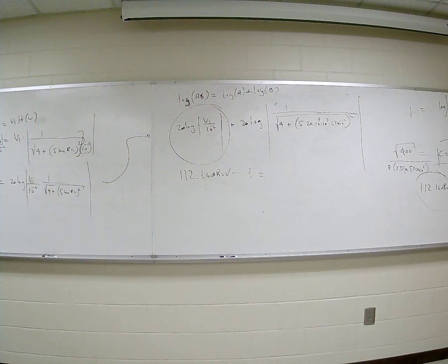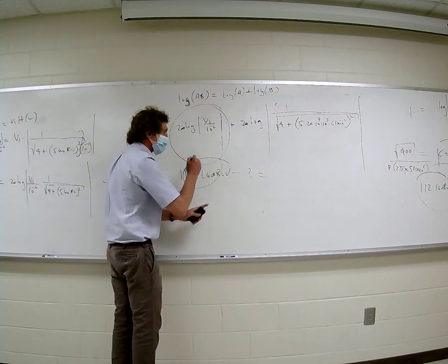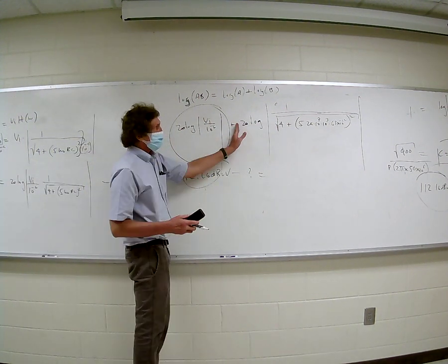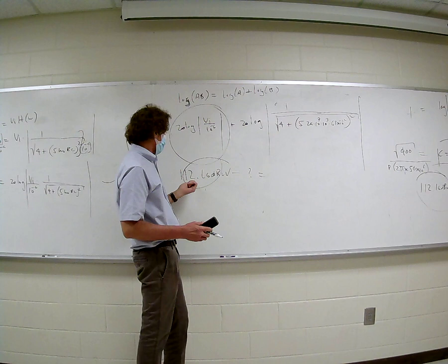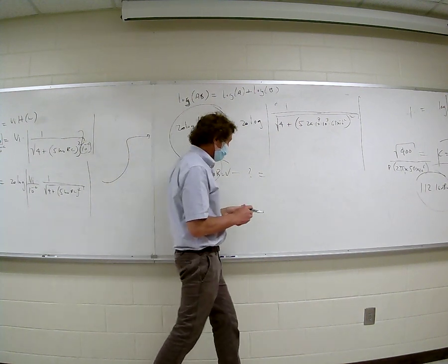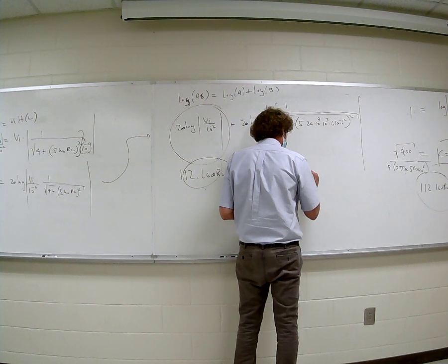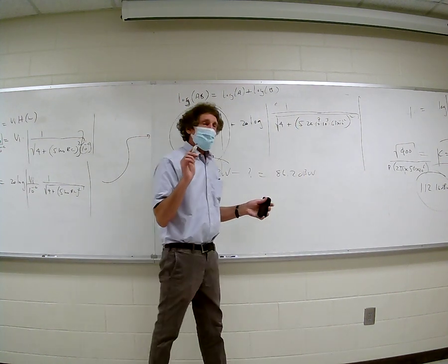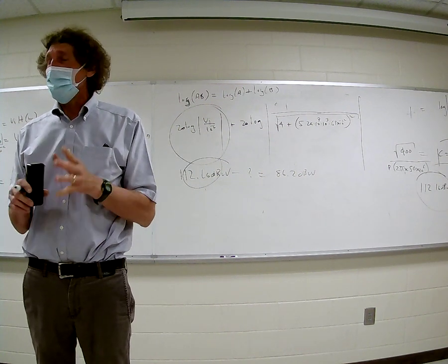132. That's not believable, because it's got to be minus some. See, this is going to be what? I got minus 26 dB for this. All right, so take minus 26 from 112, that's 86.2. 86.2 dB microvolts. Now, what did you say you got, minus 26?